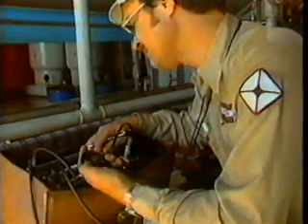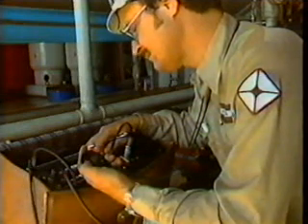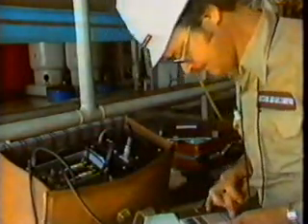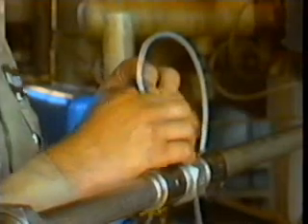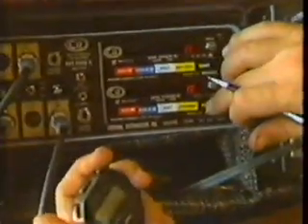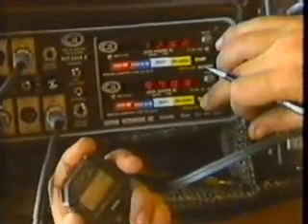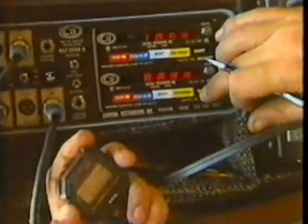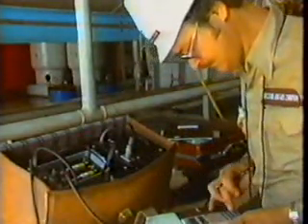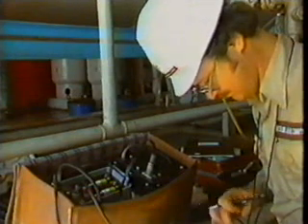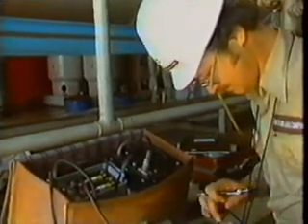Now check the master meter totalizer against the meter totalizer in terms of pulses per unit volume. Once checked, zero the master meter and attach totalizers. Gate the two totalizers together and measure the volume with a minimum of 10,000 pulses. Stop the two totalizers simultaneously, record the readings, and zero the counters for the next measure. Again, to establish repeatability, 5 out of 6 consecutive proves within 0.05% of each other are required.